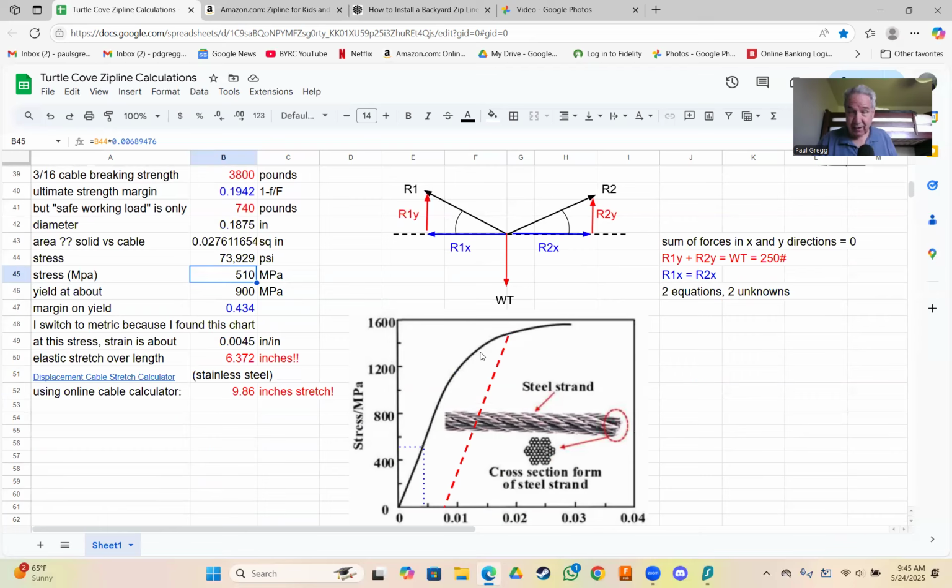It yielded, and this is a nice thing about a lot of metals, that you can go past the yield strength, but it doesn't let go. Okay, it starts to stretch, but it actually gets stronger by work hardening. Work hardened materials are stronger, but all they've been doing is they've been stretched a bit, and so it looks like they have a higher strength. So that's what work hardening is, and that's a very simplified explanation of that, and you can get a lot better information than that.